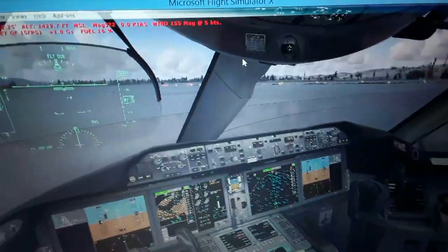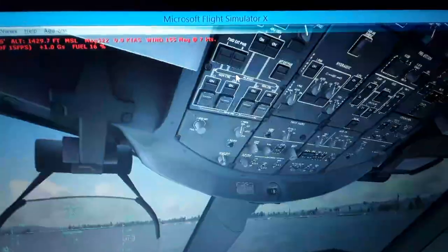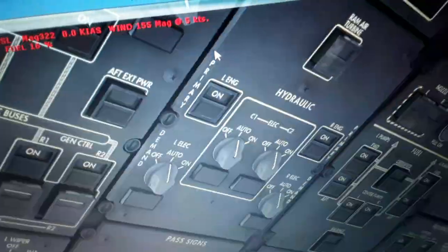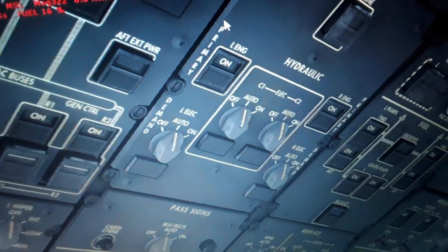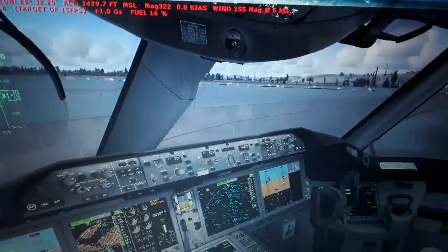So you can trim itself by flying with the autopilot flight director system panel, the auto throttle, flight management computer inputs, and flight control computer inputs. You can trim the horizontal tail of the aircraft as you fly manually, or you can leave the auto trim function. So if you have a failure of the hydraulic system that affects the horizontal trim stabilizer, the left or the right, you can see the hydraulics over here, hydraulic pumps over here, engine driven and electric driven. We're gonna have a malfunction of the automatic trim function,